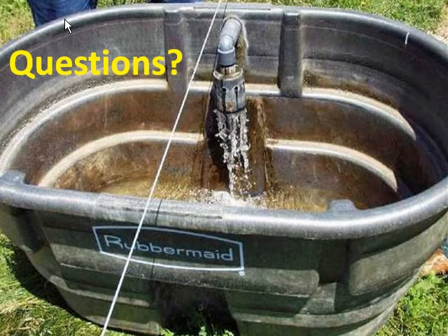I would try to choose a tire that wasn't steel belted. A lot of your flotation, your large tractor tires don't necessarily have steel belts in them. So that would definitely be a concern of mine as well. Choose one that doesn't have that.